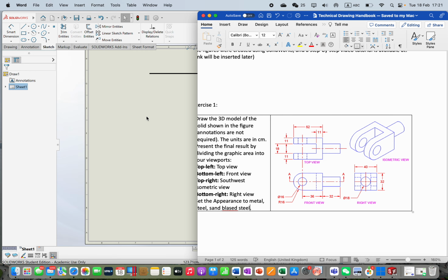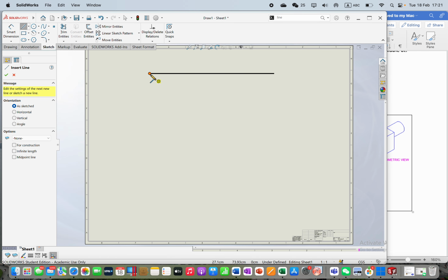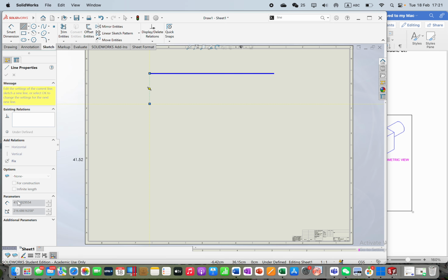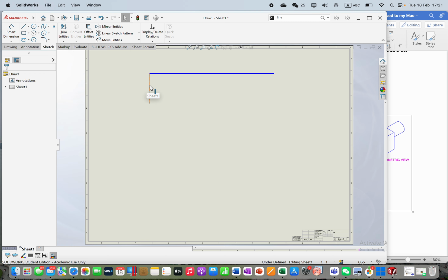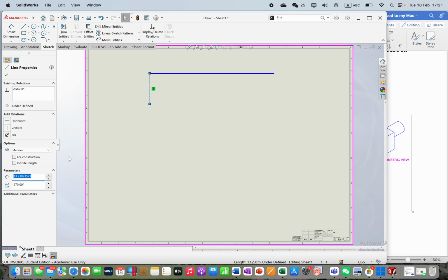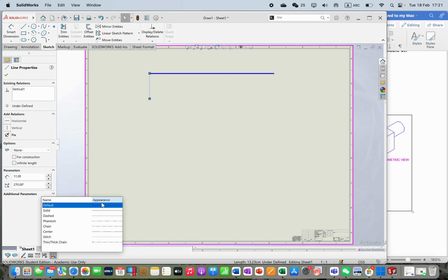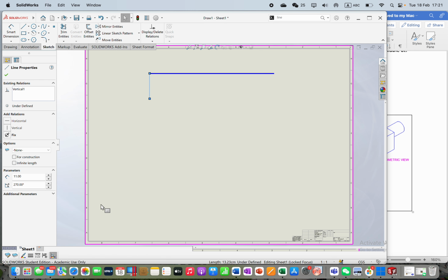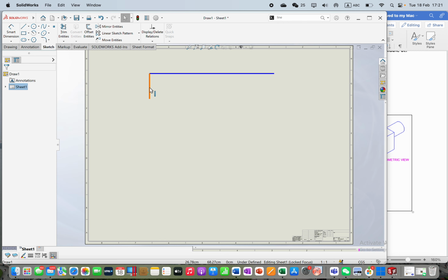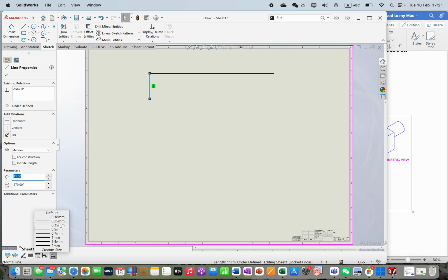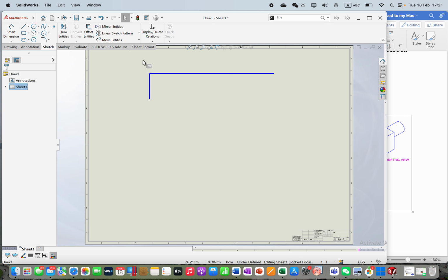Now let's do this on the side with 11 centimeters. Again, we just do this. It is straight, don't worry so much. I go here. We need to click escape when we want to close the line, if not you'll get stuck. Come again to 11. It is already designed, and let's try to change the appearance to make the default a straight line and make the default 0.5. It's a bit too big. This is not so relevant, but just make sure it looks a bit more beautiful.